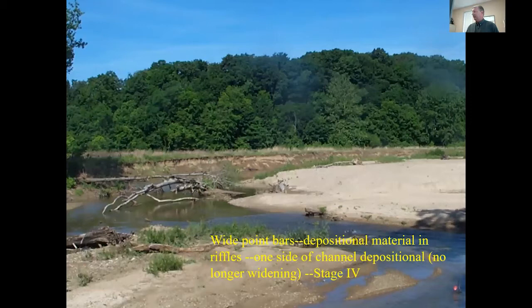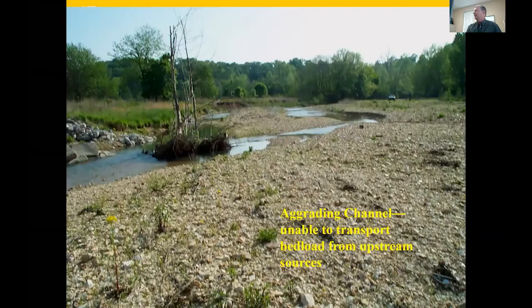Then as you get further into the stage 4 channels, you're going to see these point bars developing and depositional material starting in parts of the channel. One side could still be widening as it's finishing its meander pattern. And then you can reach this stage of quasi equilibrium where it's actually transporting and depositing some sediment in the channel, the bed load from upstream being redeposited as gravel bars, point bars, those types of things, and you're getting a more stable situation long term.